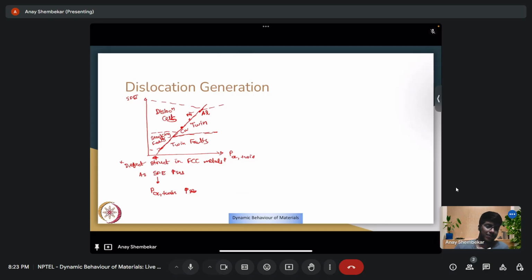And there are different ways to model dislocation generation. One of the more popular ways is using a homogeneous dislocation generation theory model, which was proposed by Myers and has certain key advantages over the models before it. Particularly, it takes the following axioms: that dislocations are homogeneously generated at the shock front by deviatoric stress, so that nucleation of dislocations ends up relaxing the deviatoric stresses involved.